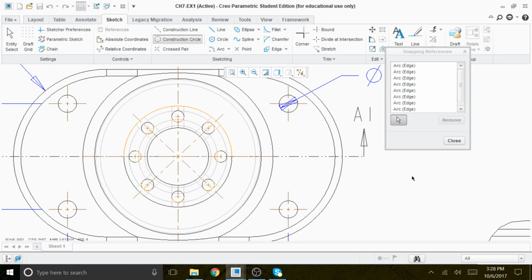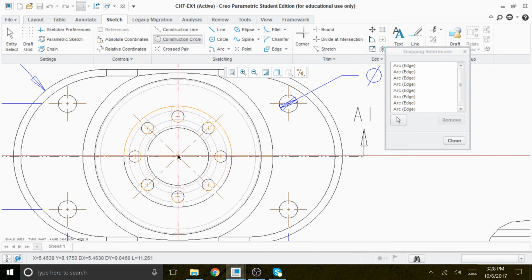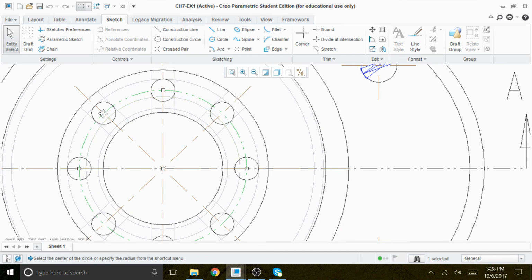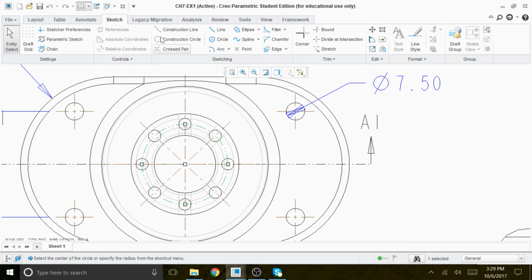Okay, when we are done, we're gonna middle click, and then we go to here to this origin center. See that? And now you can see that that is your reference, that green. Okay, that's a reference center circle. But we have to be careful now because we just made that sketch through the sketch construction circle. But in order to make that relative to this view, so we get the value of 35, diameter 35, just while it has been selected as green.